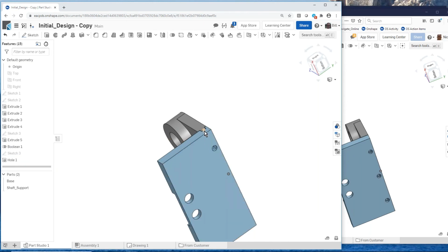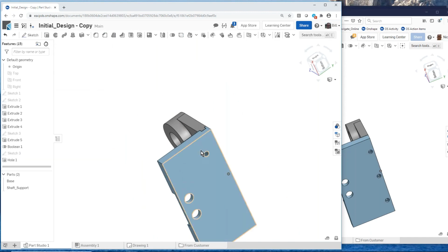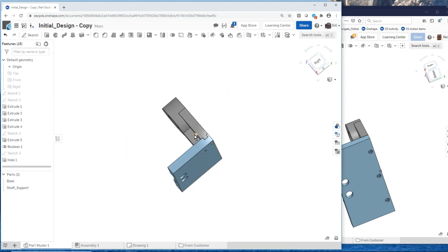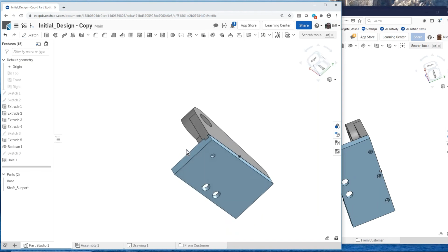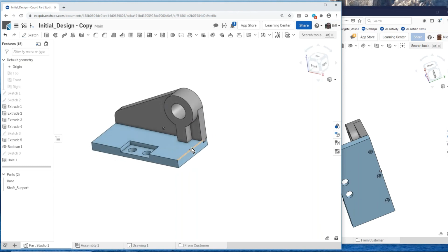And the thing is, I still don't want it going through this area here. So I can go back and change that and maybe move it out. So that moves the hole out, and it actually puts it through this guy. So now it's holding it down in this area. The screw is also keeping this from sliding in and out. And we've got really a secure design.